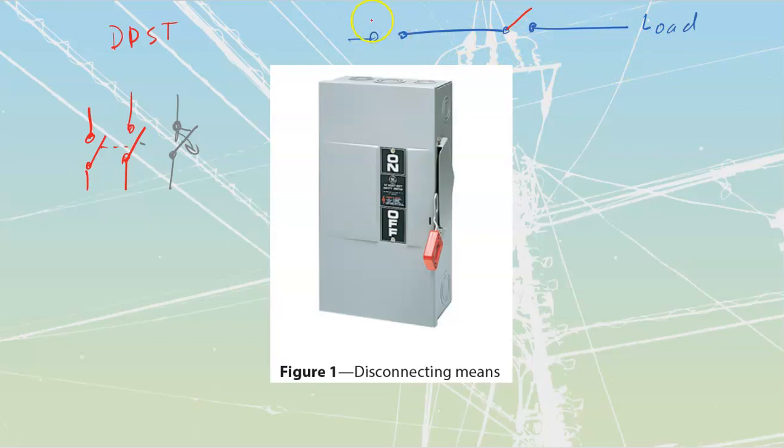We'll open this breaker up again. Open it up like that. What we'll do now with the breaker open is we'll close the isolating switch because it's not designed to interrupt or apply current. And then we will go back here and close that breaker once again. That's the whole point of that isolating switch. They never, never, never can be operated underneath load.